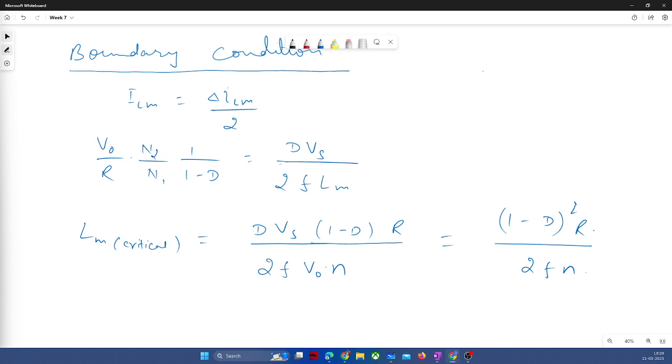While designing the converter, if you want to ensure continuous conduction mode throughout, then you will have to take the loading condition as the worst case. You take the minimum load such that if for the worst case your converter is not going into DCM, then for other cases it won't go anyway. So if you want to ensure, you have to design it for the worst case.